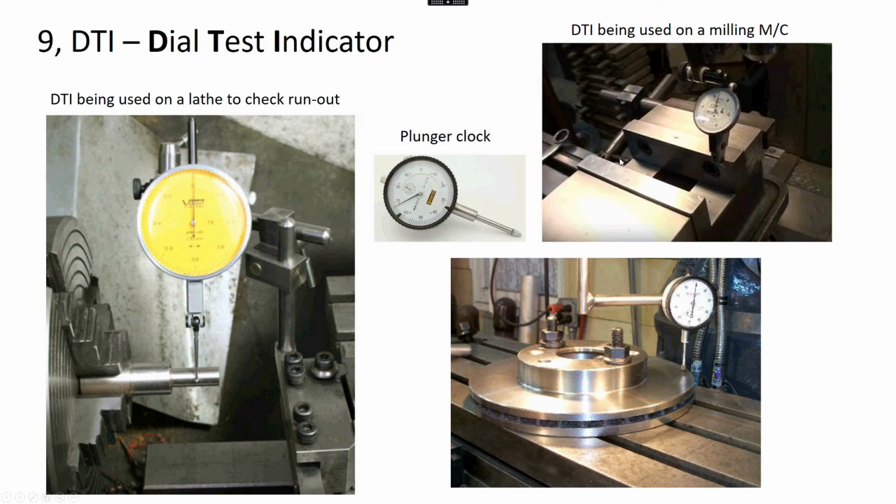So if you're milling a block in here, the way you should mill it really, you'd put the block in, you'd sit it on this face, it'd be sticking up out the top, and then you're going to mill the face. The way to mill it square would be to mill the top face, and then you turn the face you've just milled against the fixed jaw, and then you'd probably put a round bar in on the movable jaw, and you push the round bar against the part, and basically what that does, it makes sure that the part is sitting against this jaw properly, and you can shimmy it out.